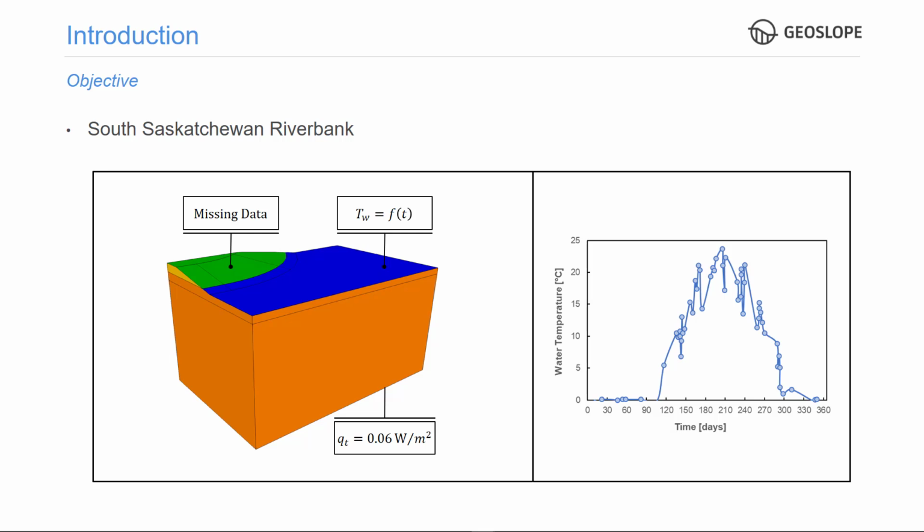Unfortunately, there are no measurements of ground surface temperature or heat flux at or near the site. We therefore have to resolve ourselves to using climate data to determine the prevailing boundary condition. The first type of boundary condition that often comes to mind in such cases is the N factor, which uses the ratio of the ground surface and air freezing thawing indexes to estimate the ground surface temperature. The other type of boundary condition that must also come to mind is a surface energy balance, or SEB.